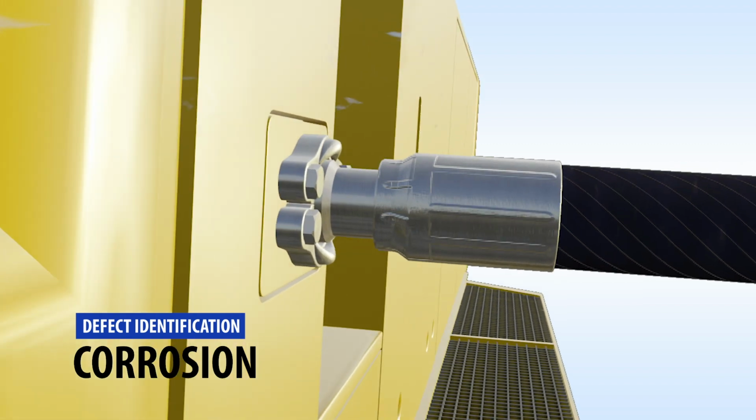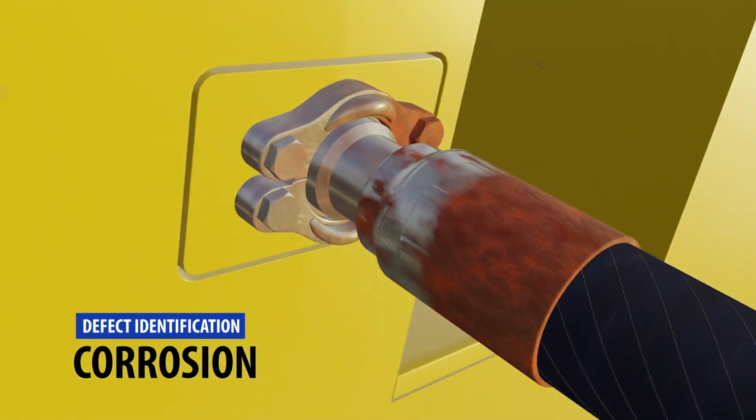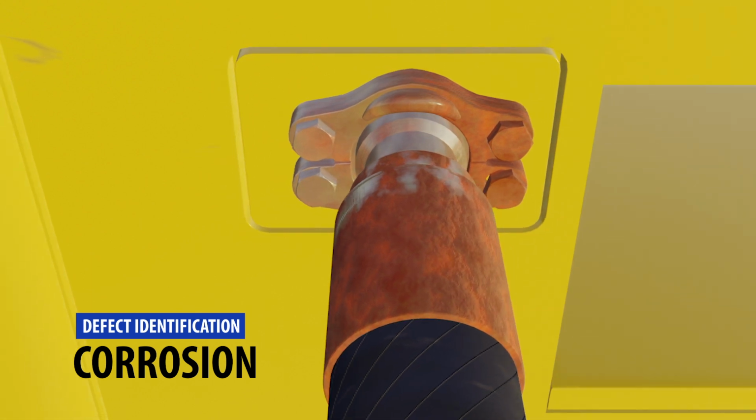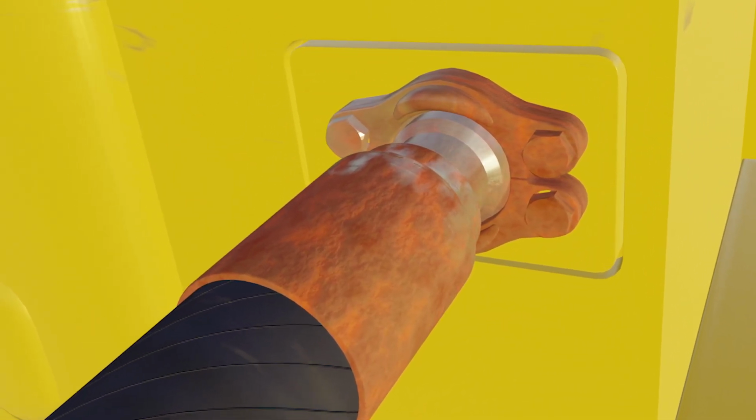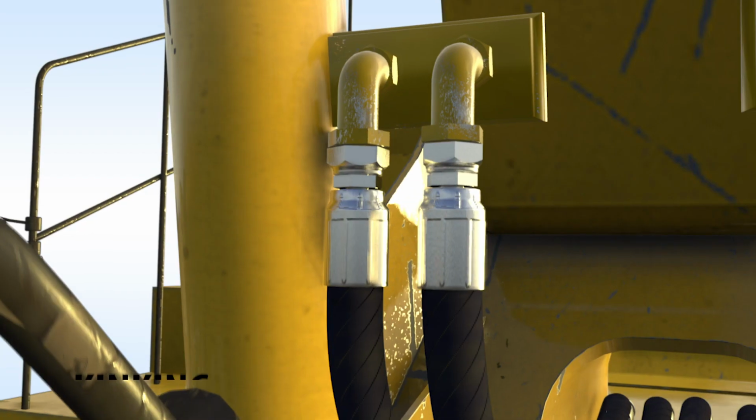The outcomes are rust or electrolysis, causing the hose to come loose from the fitting and burst as the fitting corrodes. Incorrect hose composition with wire reinforcement used in acidic environments: fluid can permeate through the outer cover and cause corrosion on the wire reinforcing.